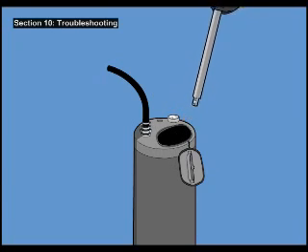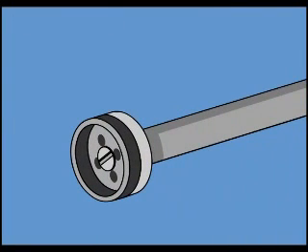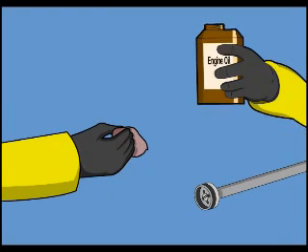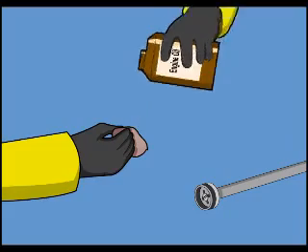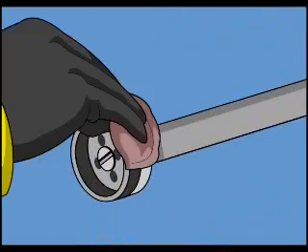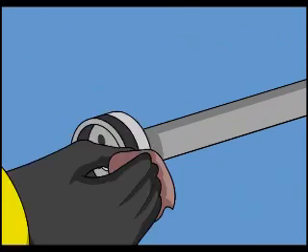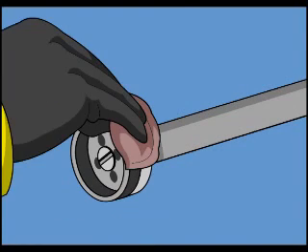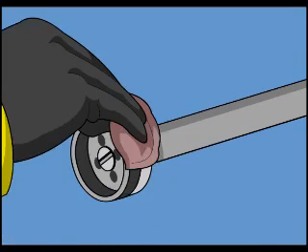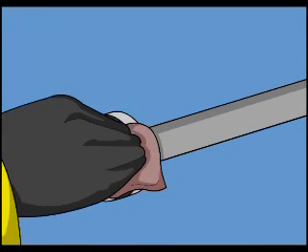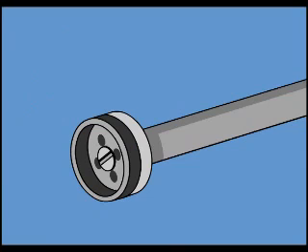Remove the pump cylinder from inside the tank. If the leather pump plunger cup is dry, soften it by rubbing in some clean engine oil. If it is damaged and needs replacing, unscrew the disc holding the plunger cap and replace. The plunger needs to be oiled weekly, not only when the pump is checked during routine maintenance.